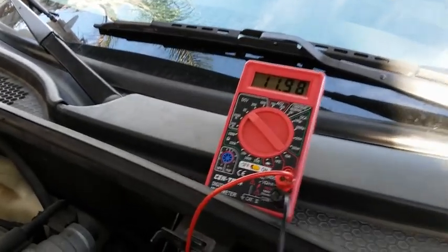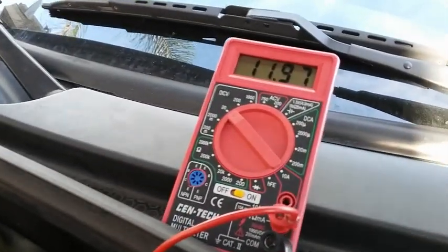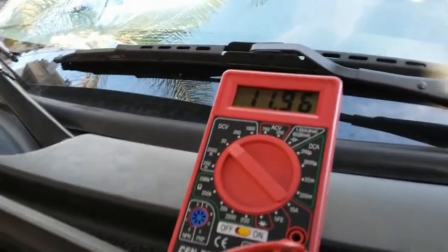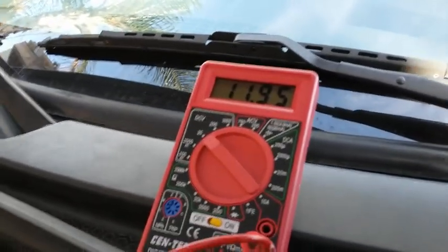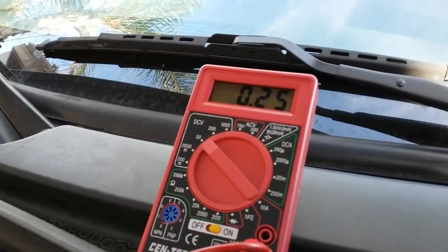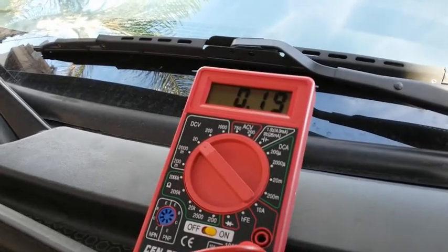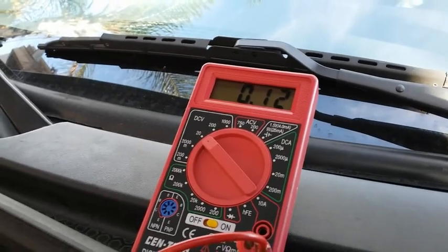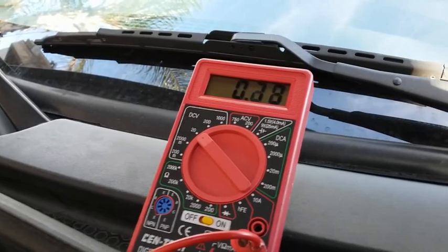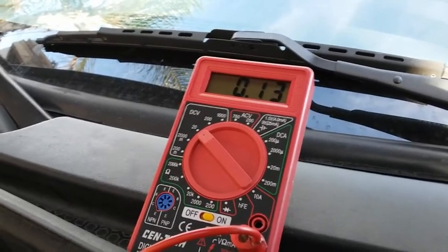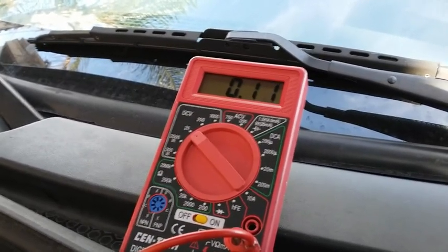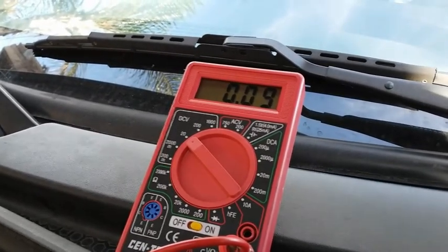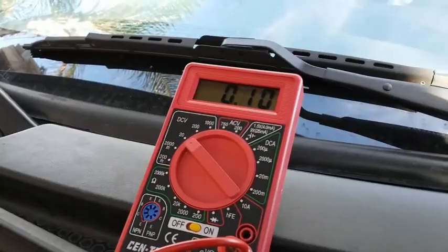So hopefully we're able to capture that glitch once again, and hopefully the voltage drops and then goes back to 12 and stays at 12, so we could see that glitch, the intermittent problem, and then hopefully we're able to capture that oil light. So it dropped after 90 seconds. It dropped back to 0. It means when this happens, it means that the circuit is working good. It means the signal in the oil pressure switch is in good condition, which is a good sign.